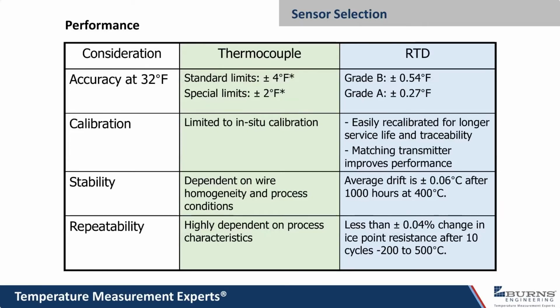Thermocouples, because of the way they work, you really need to just do a comparison calibration right in situ, right where it's located with all of its lead wires and instrumentation hooked up to it. Take a temperature standard, and if the sensor's in a thermal well, pull that sensor out, put your standard in there, measure and see what it does. That's the way you'd have to calibrate it. You can't really pull it out and take it back to the lab and check it, because it's going to be different than what it is installed in the process.